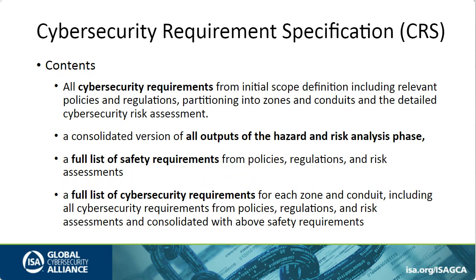Contents, you want all your requirements documented. It should be a consolidated version of all outputs of the hazard and risk analysis phase. Also, you can consider a full list of safety requirements as well as a full list of cybersecurity requirements for each zone and conduit, including all cybersecurity requirements from policies, regulations, and risk assessments, and consolidated with the above safety requirements.